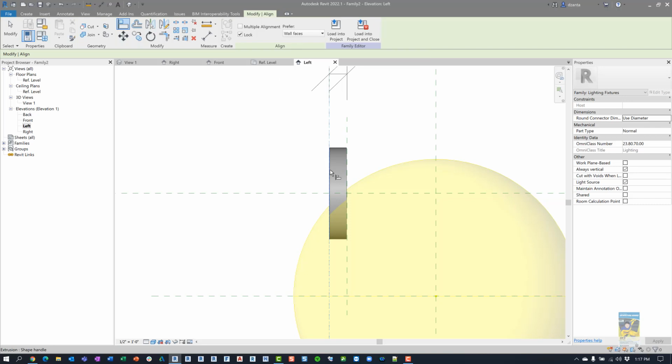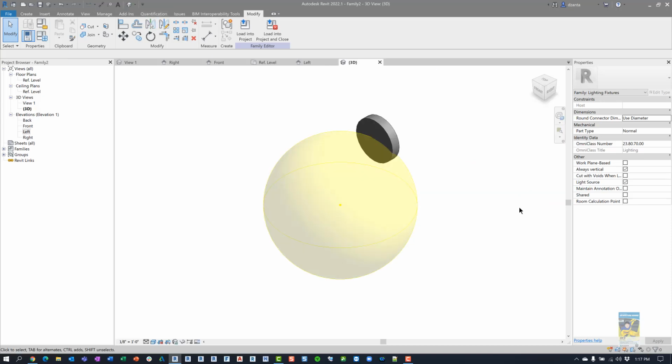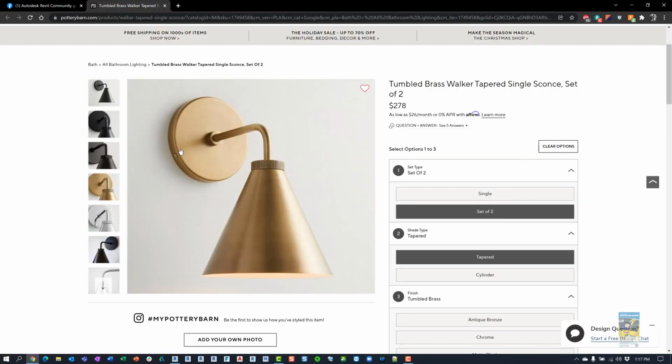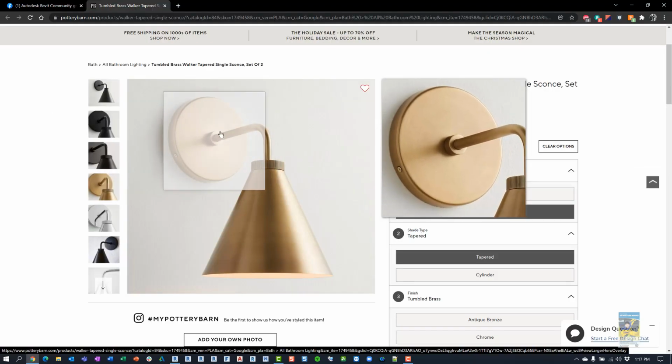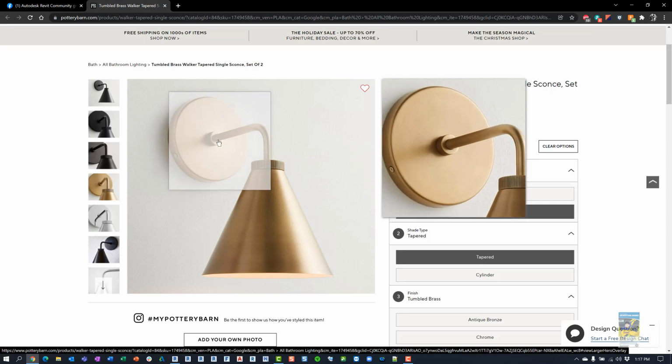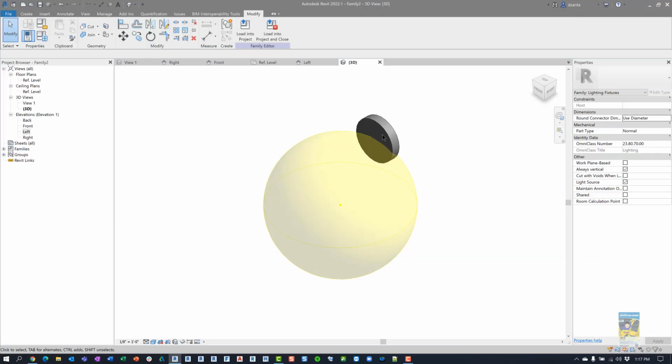So I'm just going to use the align command like this, and it's locked. This one over here as well, and it's locked. And if we just look in 3D, all we have right now is just a simple cylinder. See? And that's going to act as our base. Same kind of sequence to create this little smaller circular ring that holds that sweep.